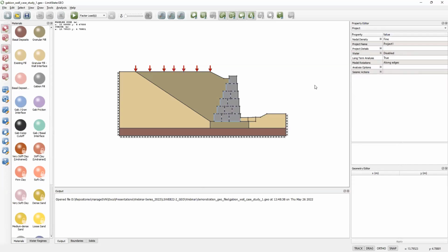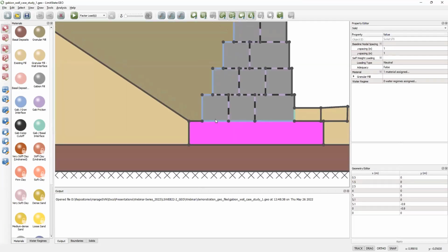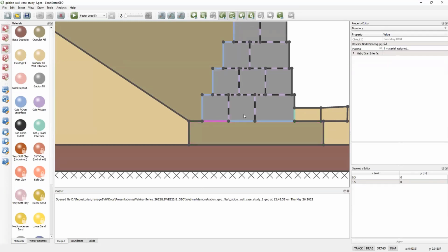So we've set up the properties. In addition to being able to set properties in bodies of soil, we can also set interface properties. Here, down here, we have an interface material, and that allows us, for example, where you're not getting full friction on the interface between a solid wall and the soil, to modify that, reducing it to 2/3 or a half or whatever is appropriate.